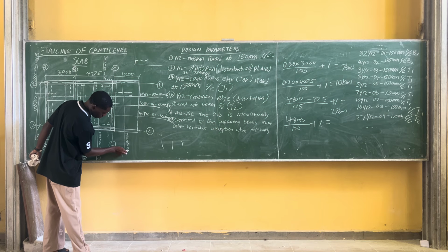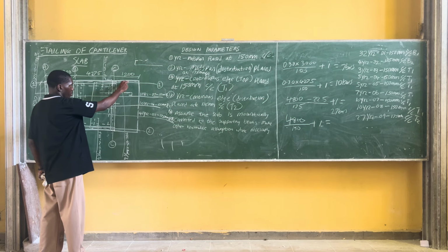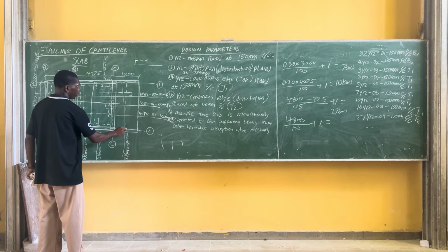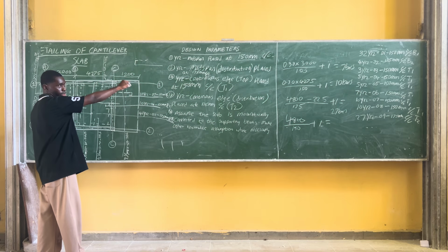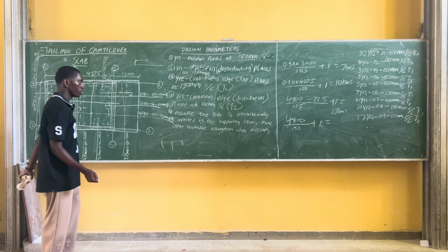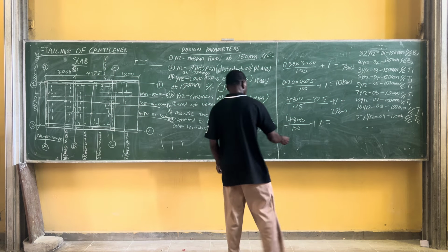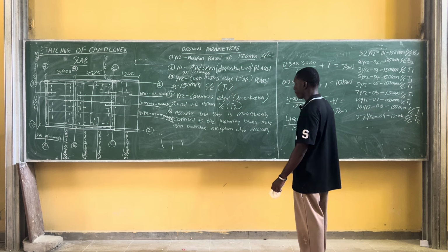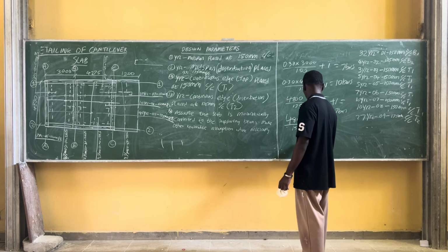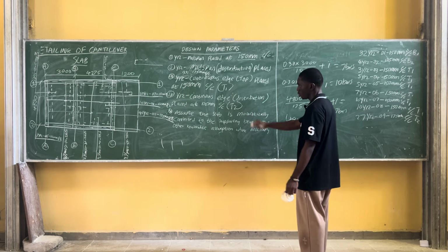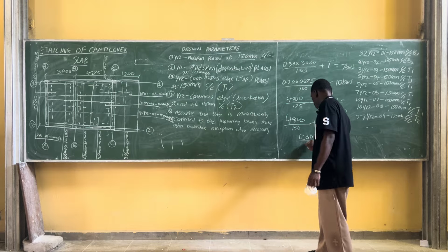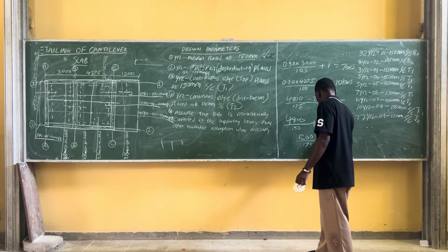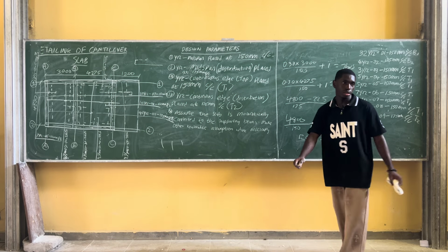150 mm center to center, T1. Our T2 is just the opposite. We just draw a straight line here, which is spanning from here to here, which is this 12,000. So I'll just do 12,000 divided by the spacing T2, 175, plus 1. What are we getting?